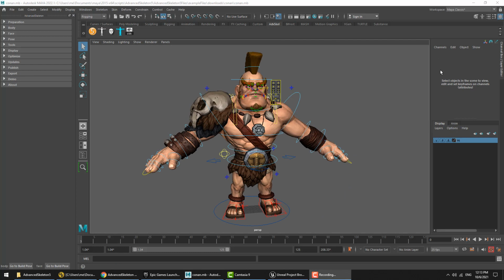Traditionally, the workflow for creating games has been to do all rigging and animation in Maya or other 3D packages, and then export to the game engine the deforming mesh with animation. Recently, Unreal started introducing its own rigging system, which allows users to start using another workflow, meaning the ability to apply animation in Unreal, or just fine tweaking of animation.